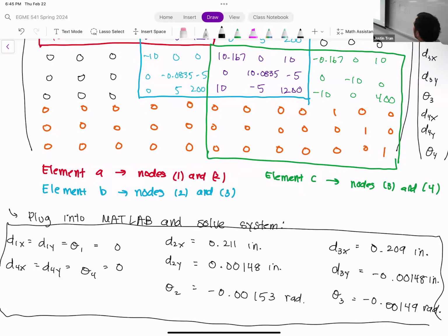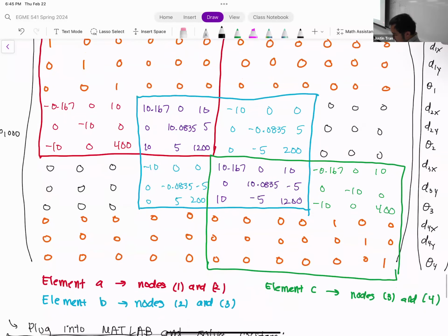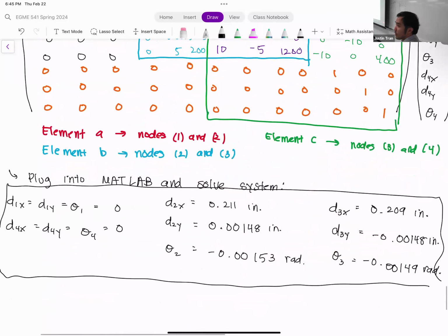Technically, you can. And so you'd basically set it up in the exact same way. So you would take your deformation solution, you'd multiply it by the global stiffness system that you did before the boundary conditions. And so actually, you know, this matrix wouldn't be viable. You'd have to kind of replug in the element A and C that we kind of already replaced with the Dirichlet boundary condition. But you definitely can get the reaction forces here. Mhm. All right, any other questions on this?